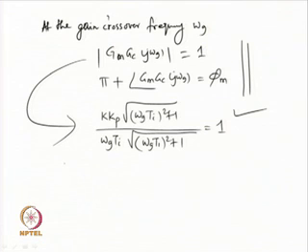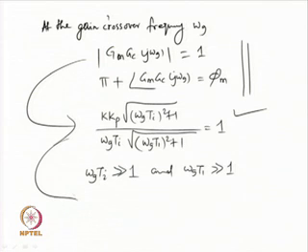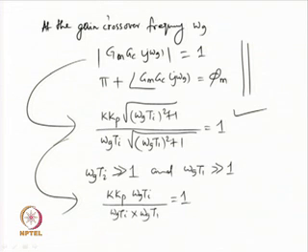They are based on intuition and theory also. It is possible to make assumptions, and with the assumption that omega g Ti is larger than 1 and omega g T1 is greater than 1, it is possible to get the same expression explicitly expressed in the form of Kp omega g Ti in the numerator divided by omega g Ti into omega g T1 in the denominator, which is equal to 1 now.